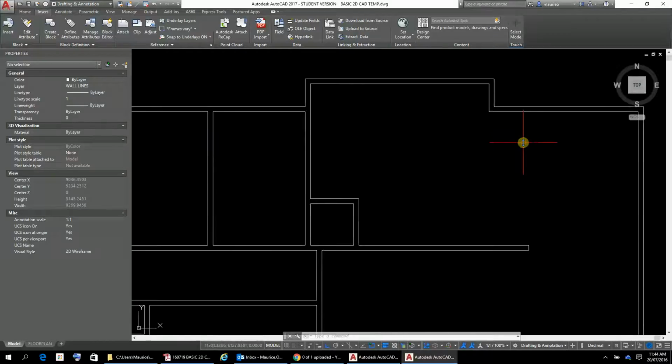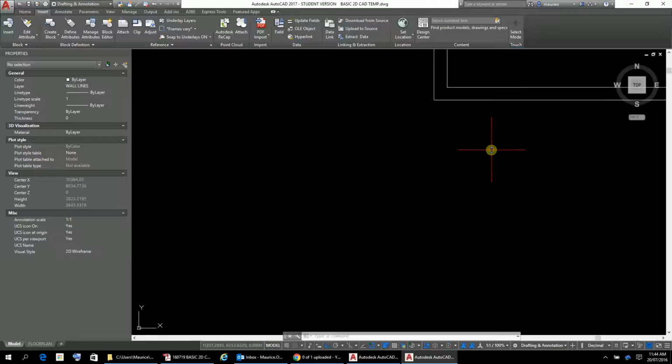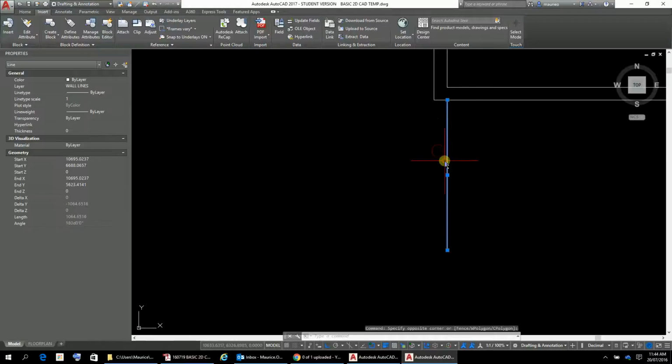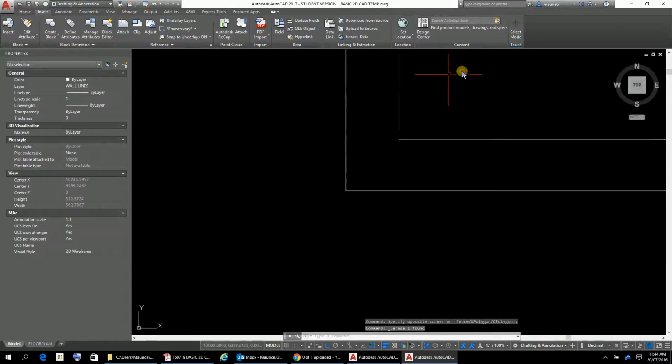Just a little thing that you might find quite useful is using the extend feature, which is something that I noticed and used. Say for instance we want to draw a line and we want the line to continue that there but from over here. So what we can do is click on there and pull it down to there using the extend feature like that. I don't know if you saw that. We just click on there, drag it down to where we want to start the line, and that's using the little extend feature, which can be quite handy at times, and I used that a couple of times in completing all of the walls.